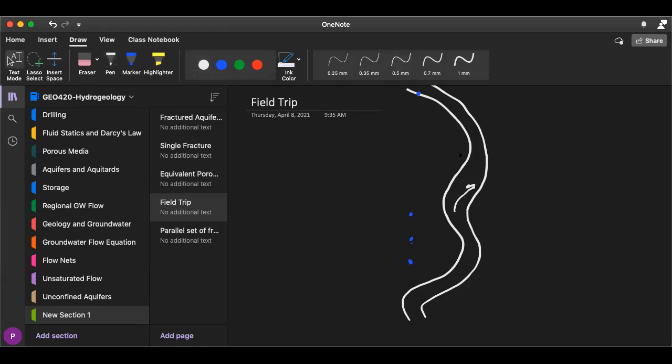I've thought a lot about this problem. You've got one measurement of the groundwater head, and depending upon where you compare your staff gauge measurement, the river up here might be higher than the wells, and the river down here might be lower than the wells. There's no perfectly right or wrong way to draw this cross section.